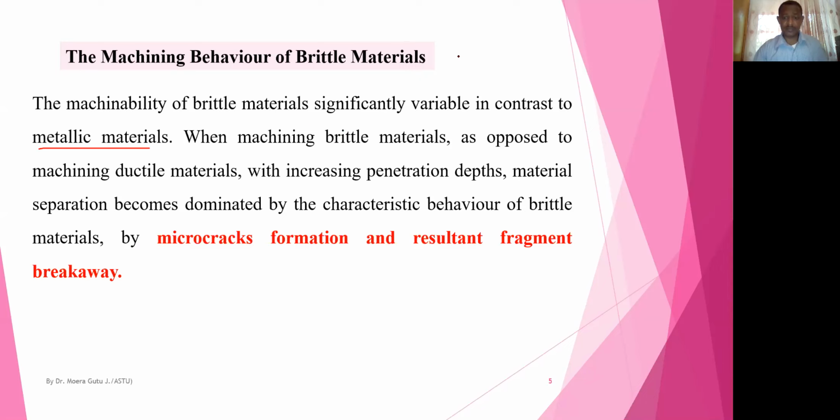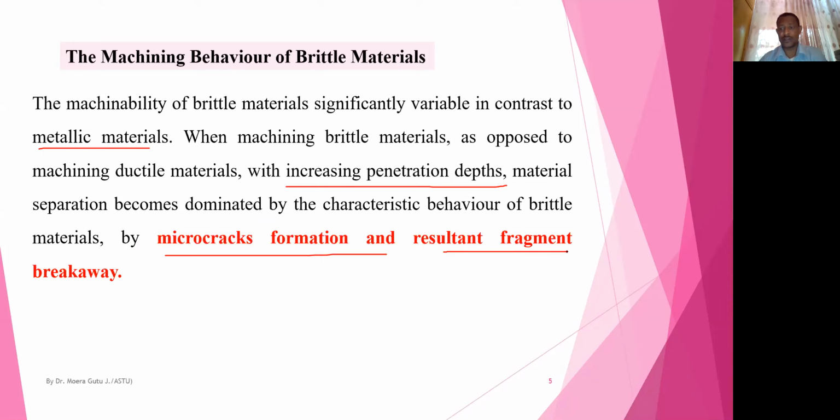When machining brittle materials as opposed to machining ductile materials, with increasing penetration depth, the material separation becomes dominated by the characteristic behavior of the brittle material. So there is a formation of microcracks and the resultant fragment breakaway of the material. So this has its own problem because the cutting tool can crack also. The machined surface is difficult to get to a required smooth surface finish. So these are the behaviors of these hard materials.